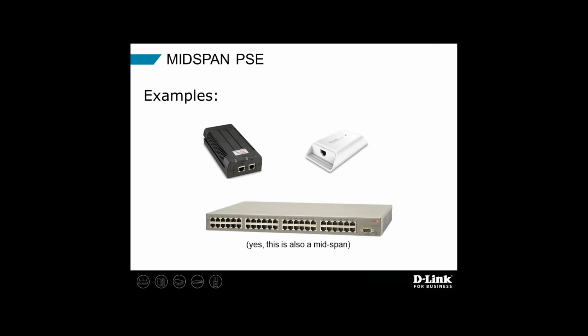Here's a couple examples of mid-span PSEs. The 2 on the top are single port mid-span PSEs, and yes, even the device on the bottom, although that looks like a PoE switch, it's not. That's actually a 24 port mid-span PSE. A mid-span typically has 2 ports, an in and an out. So the in is the Ethernet coming in, and the out is the Ethernet coming out with the PoE power also on the cable. A lot of times mid-spans are referred to as PoE injectors.